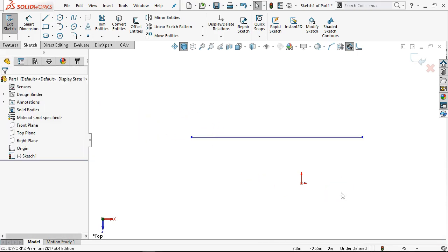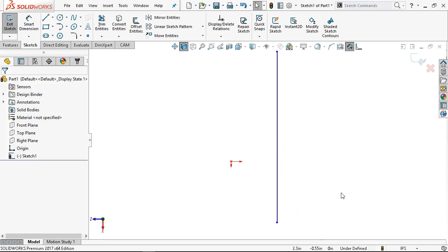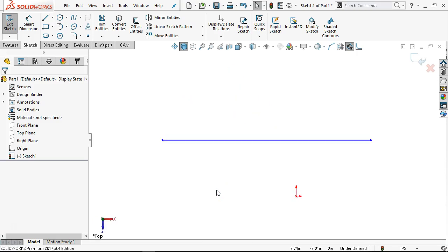And a lot of times what will happen is I will lose my frame of reference and think that, oh wow, I really needed to make that vertical. Well, my origin says that, no, that's still horizontal. I'm looking at it in a different perspective, in a different orientation. Still horizontal. Not going to get away from it. And if I go Control 8, normal to the sketch, that's going to bring it back into that orientation and help me decipher some of that information.